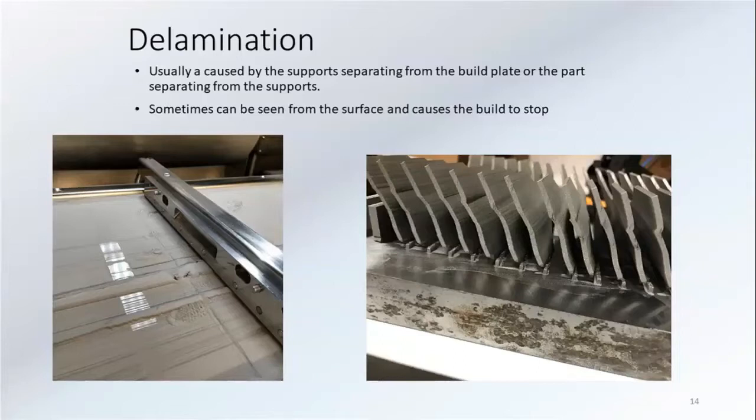What was happening is that in this particular build, I was using a soft recoater. I was using silicone, and the silicone would give as the parts would warp. So they delaminated on the edges. I did not support the edges properly. I used too thin of supports. My goal with this build was to easily remove them, and they removed too easily. So they warped on the edges.